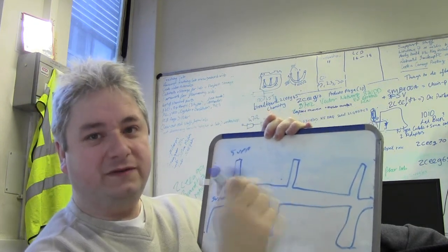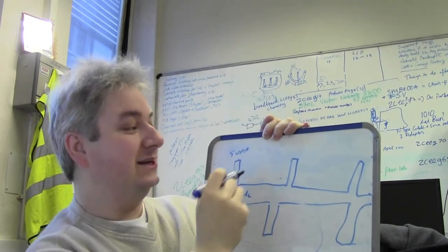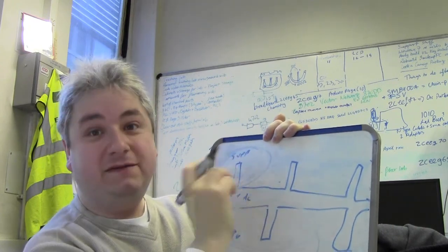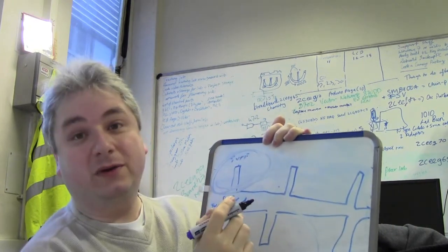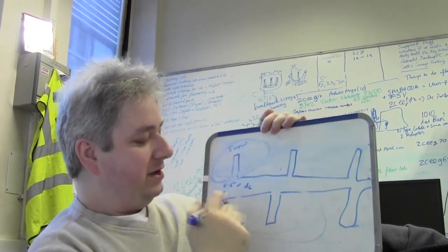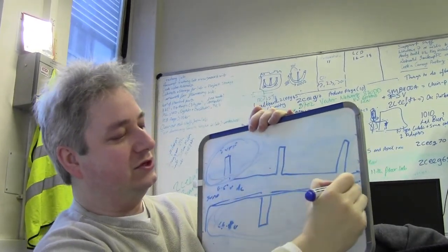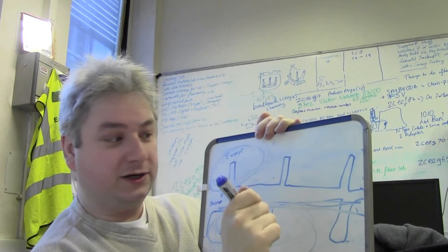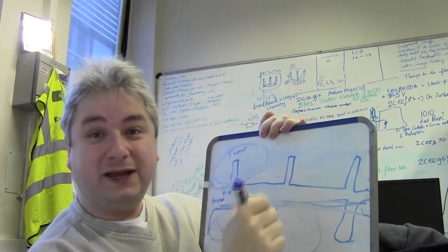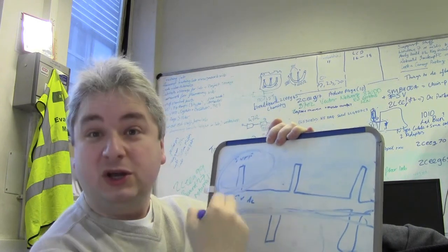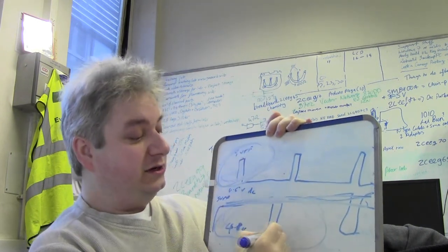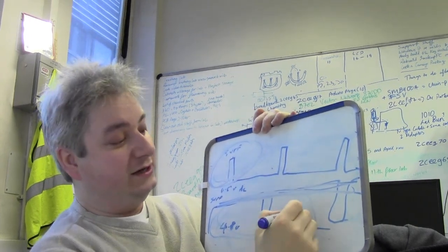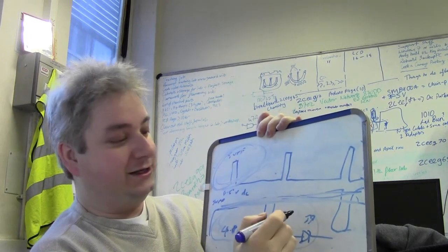Well, you're in the same scenario as before. You've either got too much power for your LED to handle, or too little power for your LED to handle. Not particularly good. If you're dimming an LED, you don't have to worry about too little power because you want your LED to get dim. But you do have to worry about when it tends towards a permanent 5 volts, because you've only got very, very small off times. So it goes back to the other two examples, where you've got too much power. So you definitely want to chuck in your resistor again with your LED just to drop that excess power.